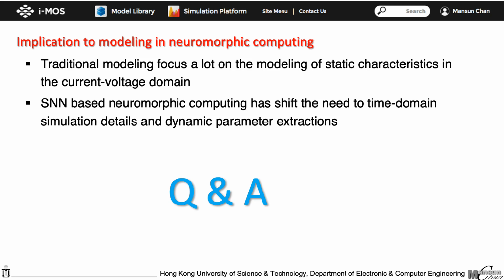However, the difficult part is really in the parameter extraction. In traditional devices, we have put our focus on modeling the terminal currents of a device with respect to terminal voltages. Less attention has been paid to the timing dynamics of the device. And timing is usually only handled by delays as a result of terminal charge and capacitance models.